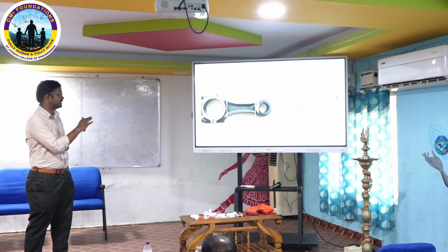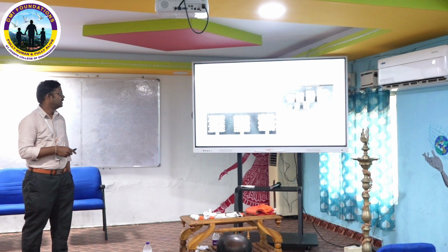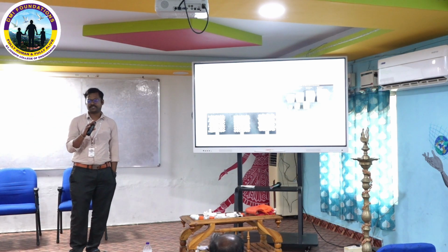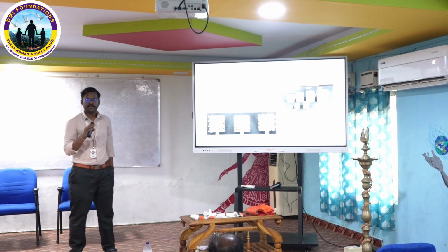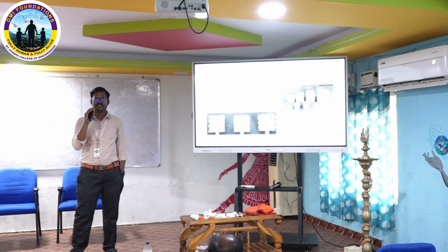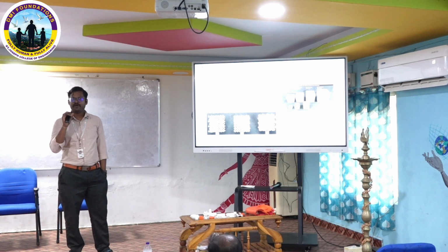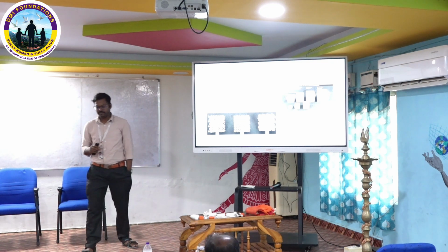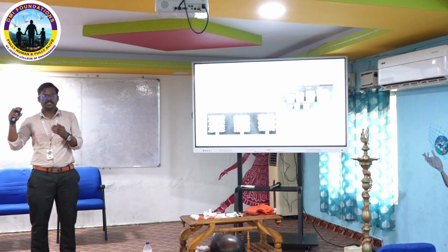First of all, in this step I selected my design space. Next, I finalize my strut configuration. If I go with a lattice strut based unit cell, I can control the cross section of the strut and the length of the strut, by which an important parameter is relative density.